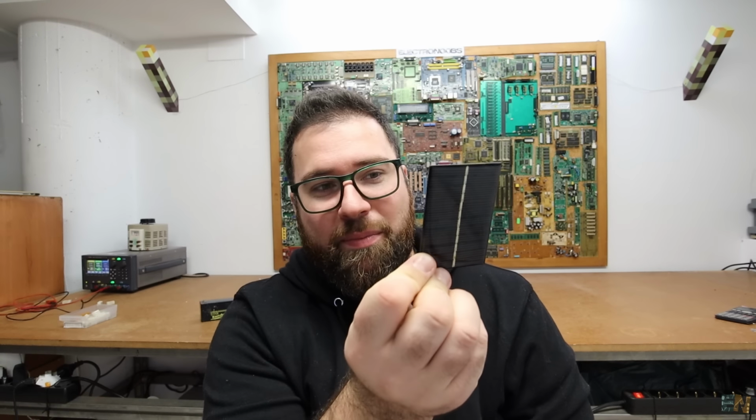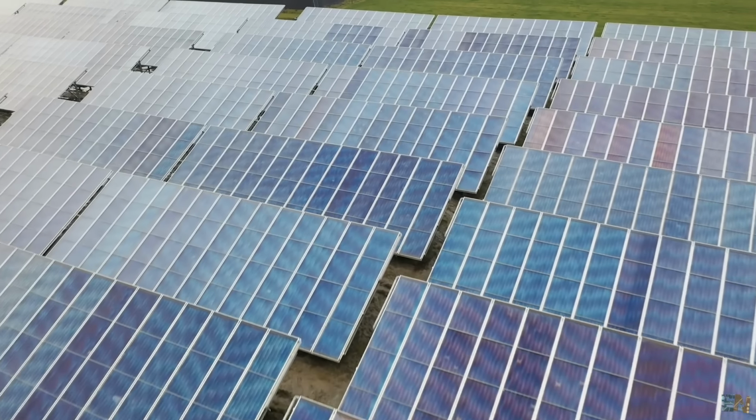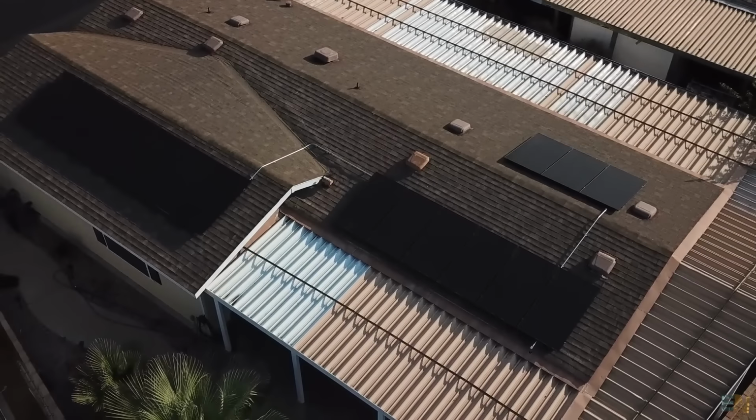because usually when you have a solar panel which is not like a toy solar panel like this one, which will go up to only 5 volts, the big solar panels that you place on top of your roof can go up to 24 volts each, and if you have four of them in series, you can easily go up to 100 volts. And the more voltage you have, the lower current you need. So if you have a system of 24 volts instead of 12 volts, you need very small wires, because if you are using less current, the wires could be a lot smaller, so it will weigh less and cost you less. So if you have a lot of wires in your home, it's better to make a system of 24 volts instead of 12 volts.